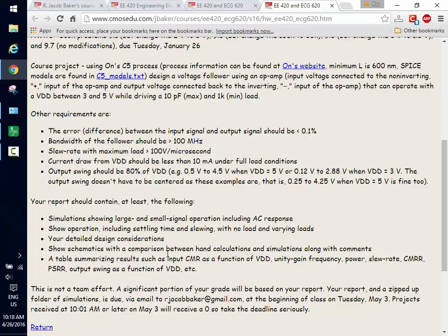So let me ask you this. Is there any way with a PMOS or an NMOS, this is going to blow your mind, that you can get an output swing that is 0.5 to 4.5? Yeah, you've got to use two diff amps in parallel so that one turns on while the other shuts off, and vice versa. So let's look at that in the chapter that you're reading. I was trying to think of that too. I was like, well, based upon our VGS and VDS data, there's no way. Well, let's discuss it further.